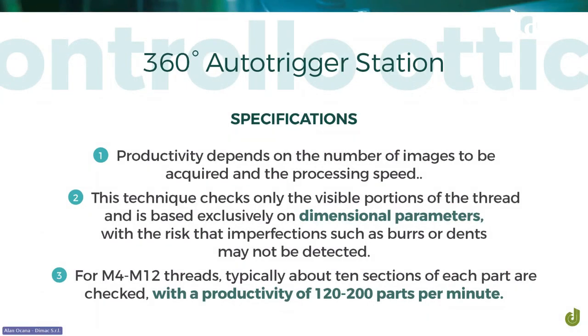Okay, so in this setup, we're using a magnet to rotate the part. That gives us a slightly higher output rate compared to mechanical tip and tail systems. And of course, the system can also perform dimensional measurements, such as outer thread diameter, pitch, and other geometric parameters.